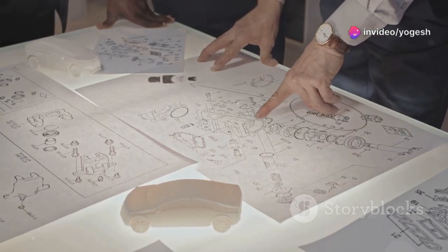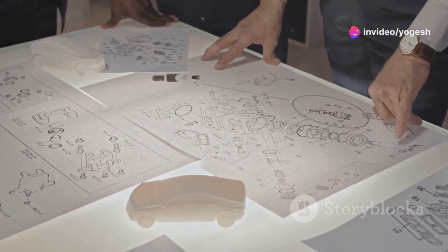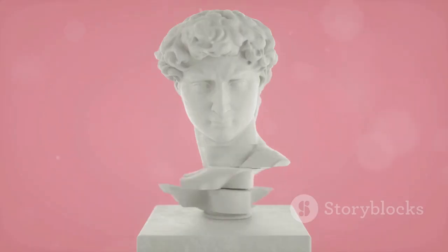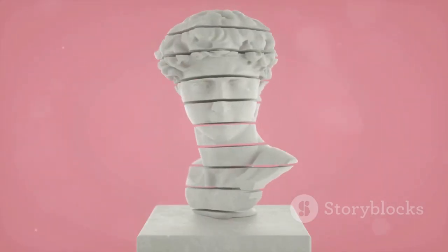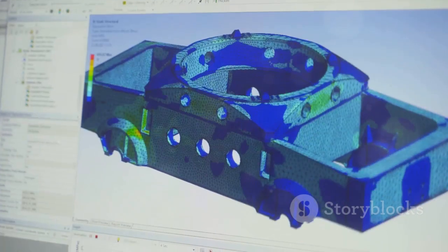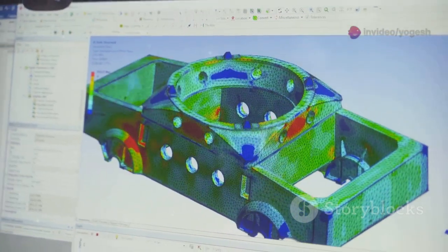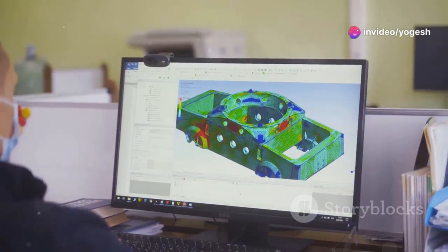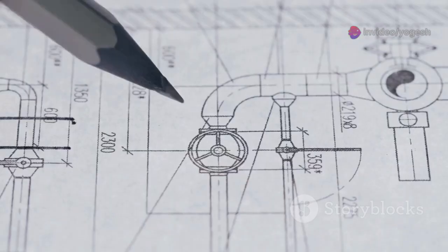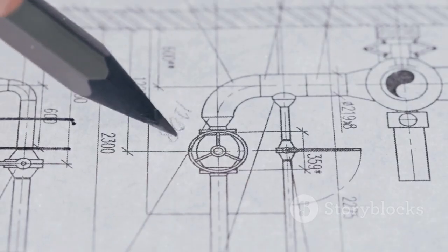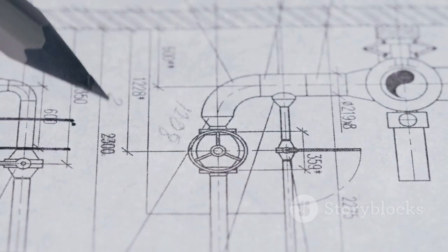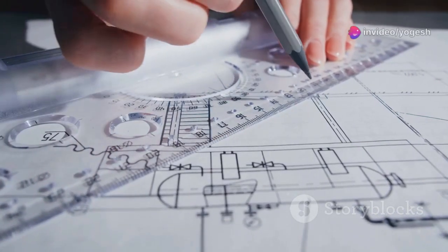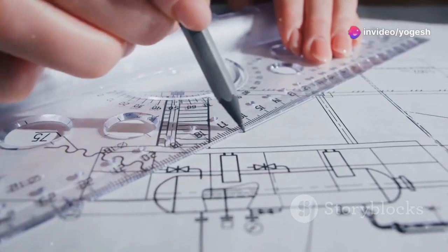This is exactly where sectional views come to the rescue, transforming confusion into clarity. Instead of leaving things to the imagination, we slice the part open on paper, just like cutting a cake to see all its layers inside. This approach makes the invisible visible. Suddenly, those confusing dashed lines are replaced by bold, solid lines that clearly show the internal features. The drawing becomes much easier to read and understand.